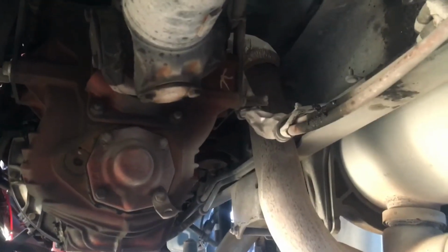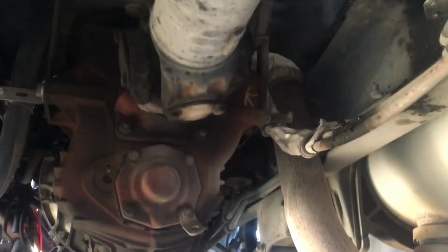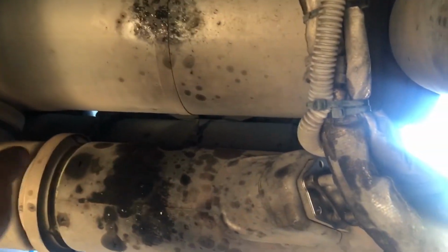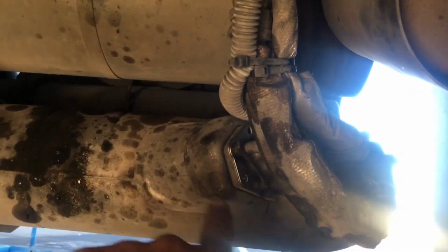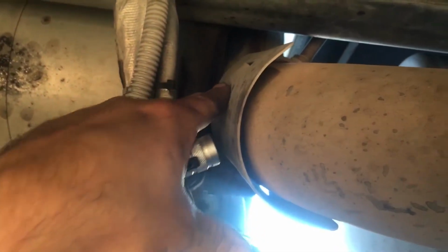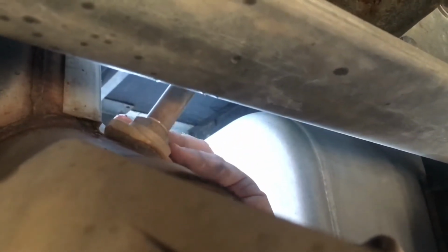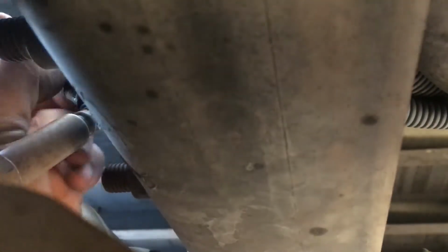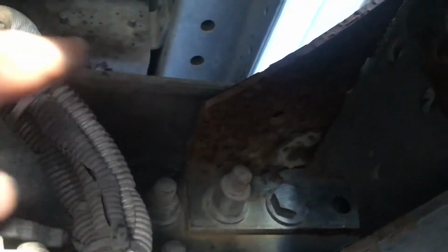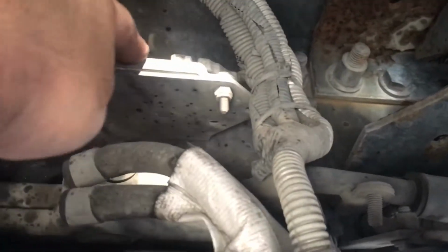So now I'm looking for my outlet NOx sensor. I'm underneath the truck. Here's the back of the transmission and the drive shaft, and right next to it is the exhaust pipe. Comes down, goes through your after treatment system, through the DPF, through the SCR. There's the doser, and here it comes out of this exhaust pipe, and you can see right here is your outlet NOx sensor, and the wiring harness runs up and above over the frame, and then back down and mounts right here.